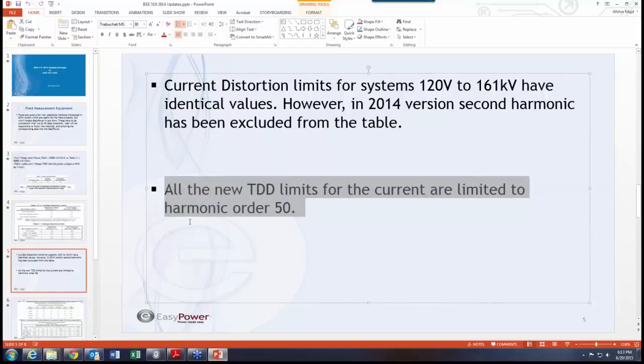How many systems, or let's say VFDs, have you seen that have a major harmonic contribution above the 50th order? The 50th order in a 60 Hertz system is going to be like 3K Hertz. It becomes high frequency, more or less, at least to us as power engineers.